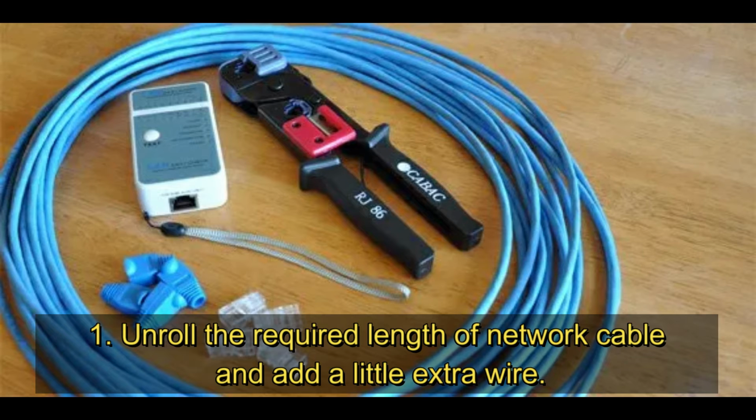If a boot is to be fitted, do so before stripping away the sleeve and ensure the boot faces the correct way. Please note that the cable length should not be more than 100 meters to prevent attenuation. Attenuation is the degradation of signal strength due to losses as signal travels down the length of the cable. Keeping the length within 100 meters from the access point to the patch panel or network switch will ensure good signal strength or quality.